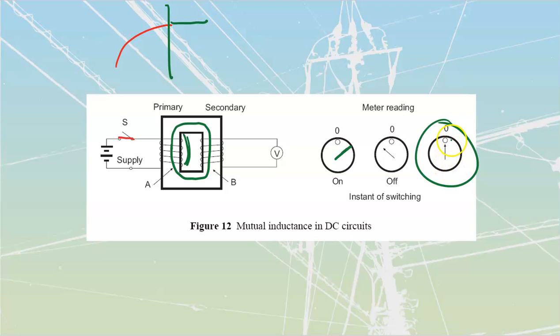When I drop my voltage on the supply side, what I'm going to have is those lines of flux which have been pushed out, which are now going to cut back in. And as they cut back in, they're going to be cutting in the opposite direction. Before they were expanding, now they're cutting back in. And because they're cutting back in the opposite direction, it's going to induce a voltage in the opposite direction.